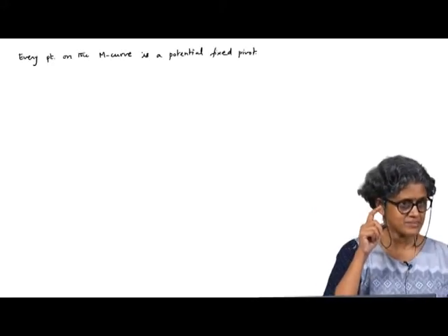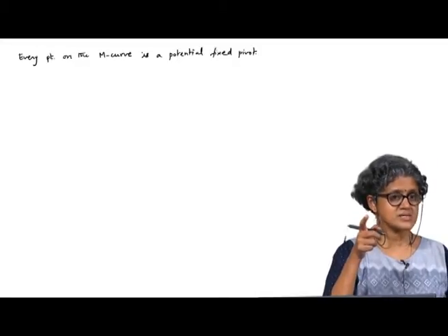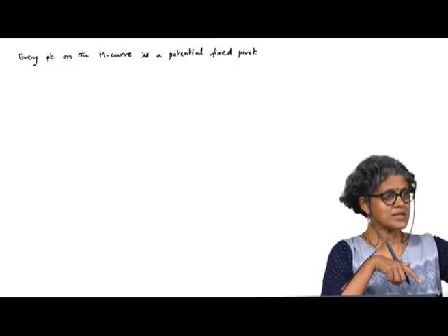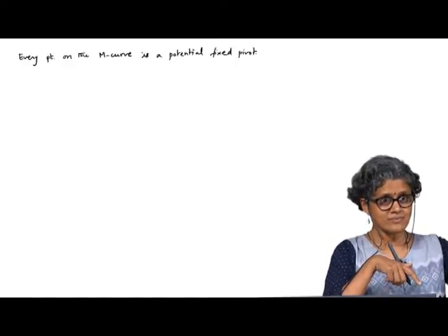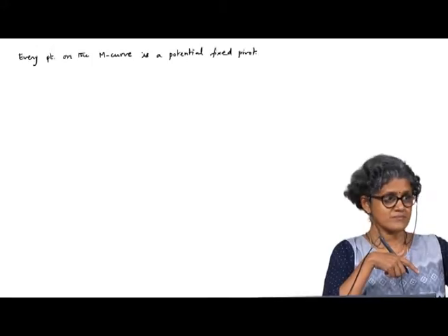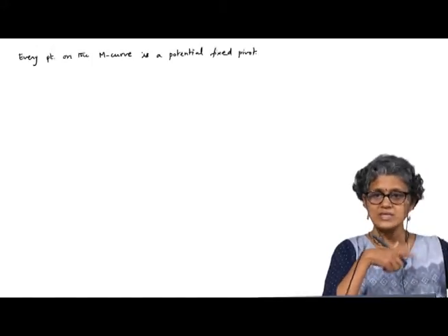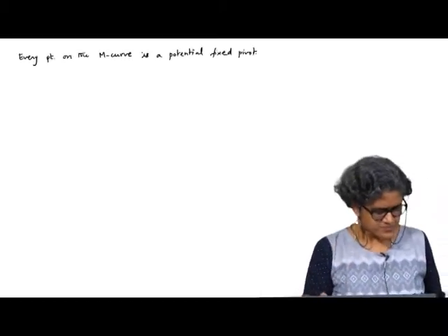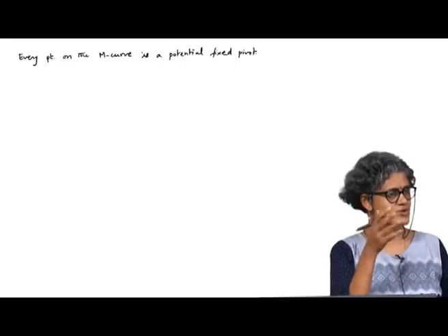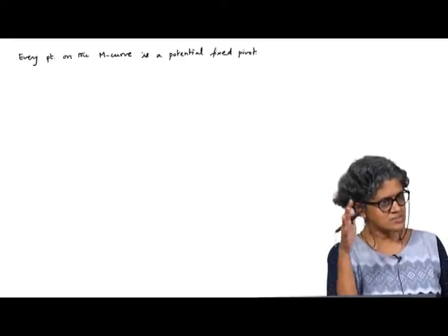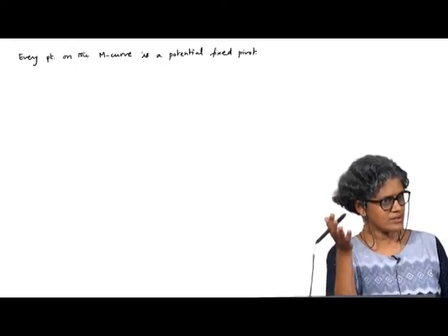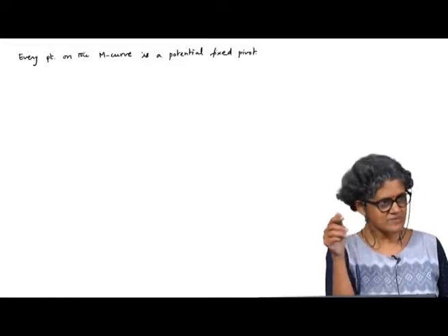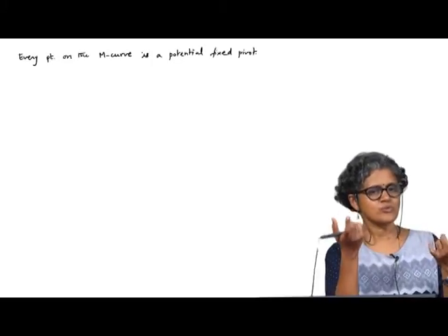Once you do that, the corresponding circle point gets fixed. So, you cannot pick any point on the center curve and any point on the circle point curve. You can choose one or the other, because only then your compatibility condition will be solved. Then you can form a dyad for one side. Similarly, choose another center point on the curve, find the corresponding circle point, you have a second dyad, you can form your 4 bar.